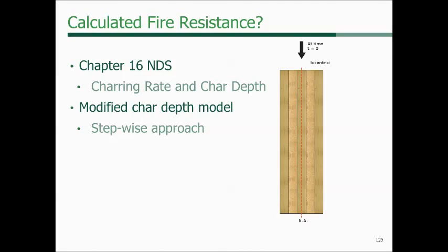Now, the one thing I also want to point out is related to calculated fire resistance. Using Chapter 16 of the NDS, we calculate a char rate and a char depth, and it's a stepwise approach to calculating the fire resistance.